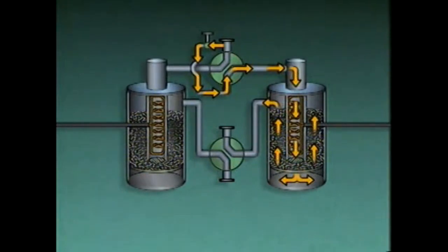However, a portion of the dry gas is routed through the regeneration tank to help dry the desiccant in that tank. The heating coil in the regeneration tank is energized to heat the gas that passes through the tank. The hot gas then dries the desiccant in the tank. In this example, the gas that leaves the regeneration tank is vented to atmosphere through the waste gas outlet.